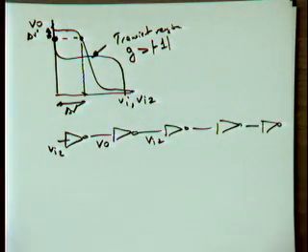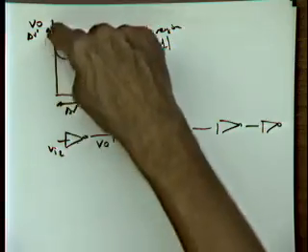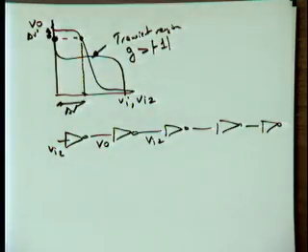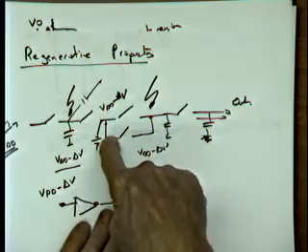And you can easily show that the more gain I get in the transient region, the steeper the transfer characteristic, the better the regeneration is going to be. So that's the whole idea: if you have a gate which has gain in the transition region, larger than 1, you will see that noise will disappear. This network has no gain whatsoever.